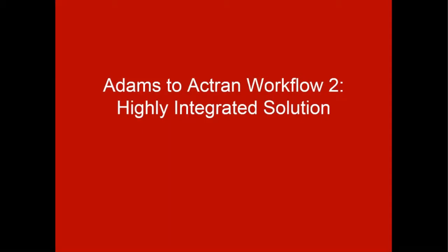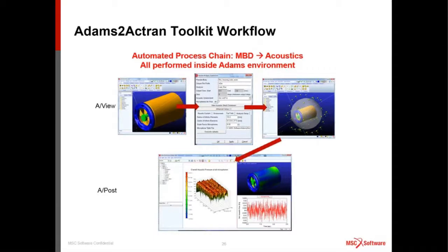The second workflow or technology we want to introduce is a different approach. We call it a more highly integrated solution. For this toolkit, what we basically did is an automated interface that embeds Actran simulation into the Adams environment. The main difference between this toolkit and the previous toolkit is that you can perform the acoustic analysis in the Adams environment, and you can get some preliminary acoustic results in the Adams post-processor.